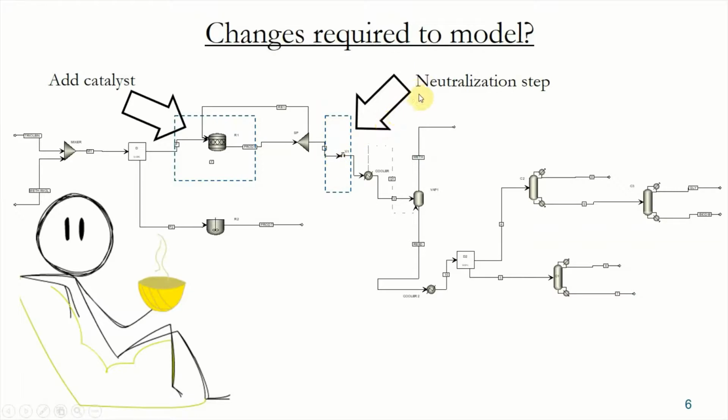So we're going to introduce, say, NaOH or Ca(OH)2, so an alkali, right, to neutralize the acid to form a salt, right? So if we use Ca(OH)2, in this case, with H2SO4 it should produce what? CaSO4, right? So calcium sulfate, which is also called gypsum. Now it's insoluble, so it can easily be removed from the mixture, right? So you can remove it from the mix, right?